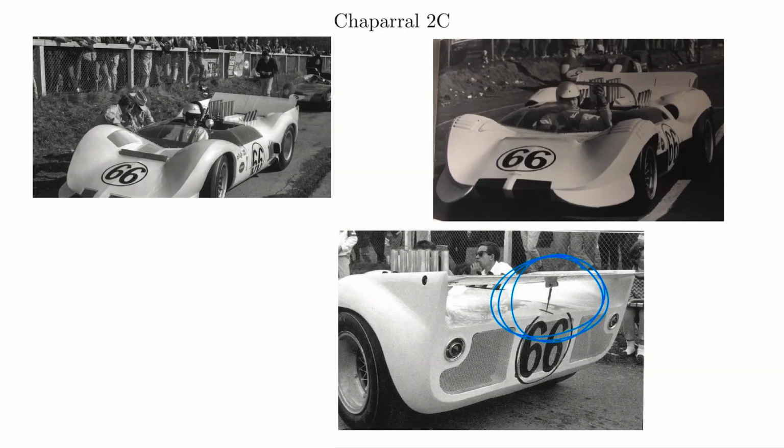What we can see if we look at the back of this vehicle is the first time they have a movable spoiler. So they're starting to piece together what we talk about in section 7: when you're generating downforce, you're also generating drag, okay? Now, you definitely want the downforce to increase your speed and decrease your lap times, right? But in getting better cornering, you want the downforce on the corners, but you don't want it on the straightaways. You don't want that drag on the straightaways, and you don't need the downforce on the straightaways.